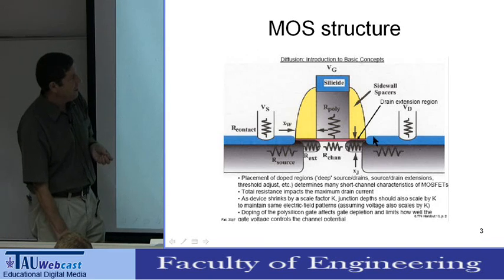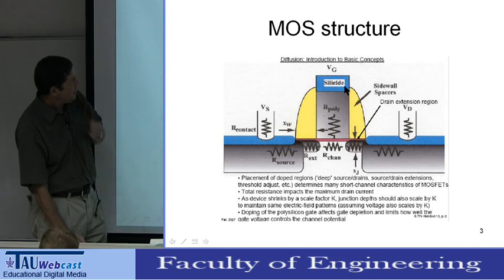The reason we use silicide is to reduce the resistance. This serial resistance can be significantly reduced by the presence of the silicide. This is the gate, and a typical gate is conducting, made of polysilicon, with a very thin layer of silicide on top. On the side of the gate, there are two spacers. The yellow sections are the spacers.